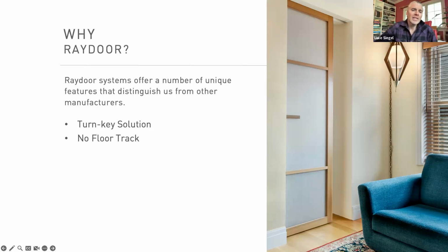The other big thing is the lightweight design permits no floor track. So all our systems specialize in not requiring a floor track. Now you can use them. There's times where they make sense, but from our stacking walls to our sliding doors and doors that turn corners, you don't need a floor track, and it's a big advantage, both from a standpoint of design, in really having a space be a creative, flexible space. You don't want to have floor tracks running on the floor, but also eliminating that as a mechanical fail point and a way that you can create a trip hazard and also degrade the value of the interior when you have to rip into a nice floor.